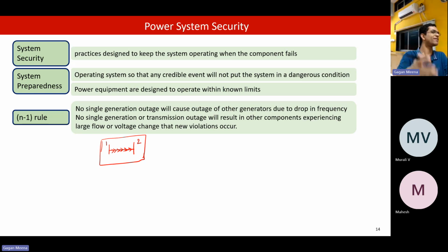Even in the same day, the thermal limit changes. It is not constant through the day because it depends on temperature also. If the temperature outside is high, then the thermal limit will reduce, because heat transfer is not much when the outside temperature is very high. It requires a temperature difference for thermal conduction.